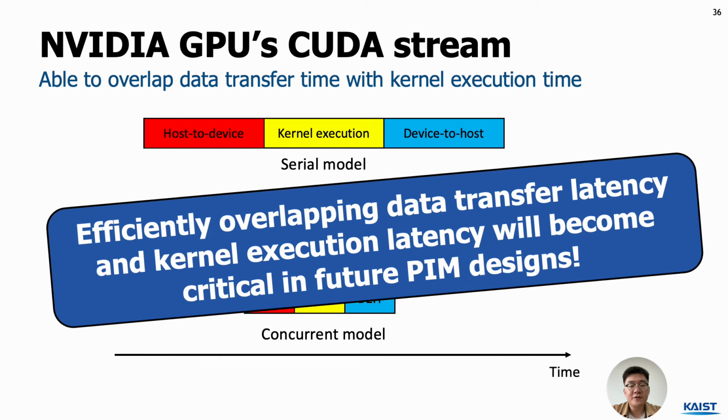We believe that a future version of the UPMEM hardware-software stack that supports flexible kernel partitioning and task scheduling, similar to NVIDIA GPU's CUDA stream, can help alleviate such inefficiency, one which we believe can be a good use case of our UPMulator for architectural exploration.